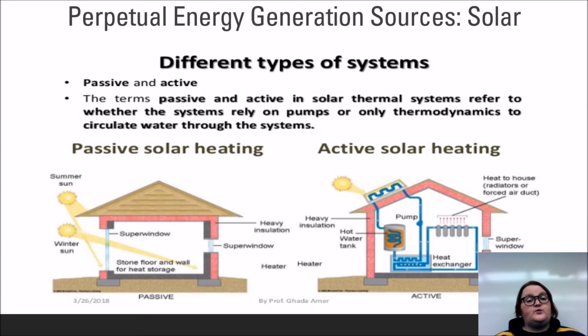Double-paned and insulated windows can keep excess heat out during the summer while retaining heat in the winter. Effective insulation within walls does the same things. Other options for these structures include stone floors and other items that can absorb heat throughout the day and then radiate it back later. Active solar heating is used when the sun's energy actively increases the temperature of something, in most cases water, that is used within the structure via a pump.